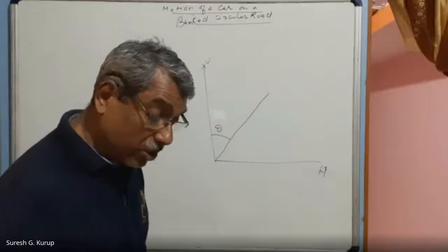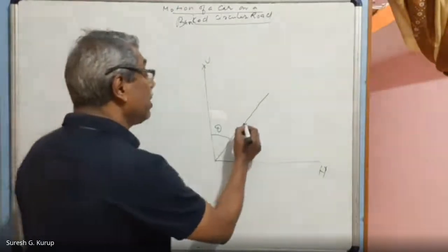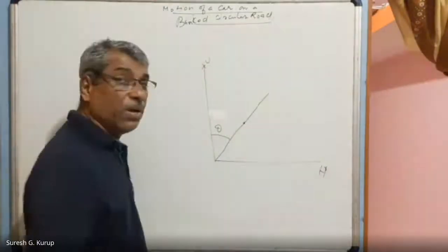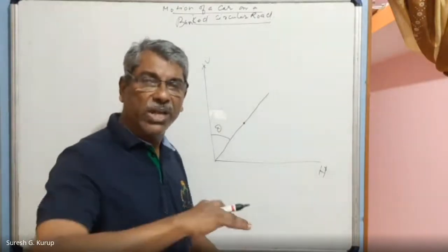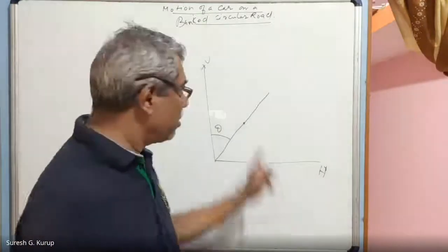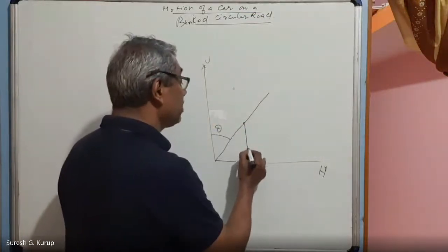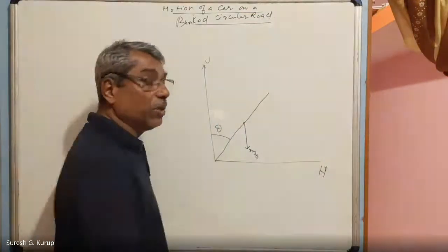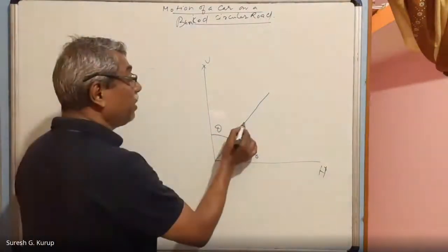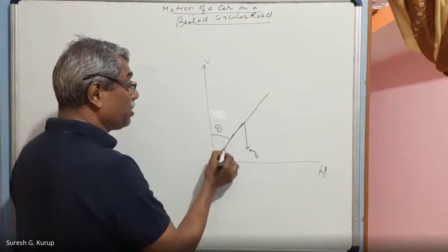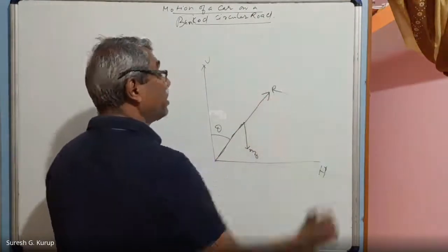This is the condition. Suppose this is the central system, the center of the system, meaning the vehicle, the cycle, and the man, with that center of gravity. So that is this point. Through the center of gravity, the entire weight is acting, this is mg. Am I correct? And suppose the vehicle is touching the road at this point with a force, therefore a force of reaction is acting along this direction.